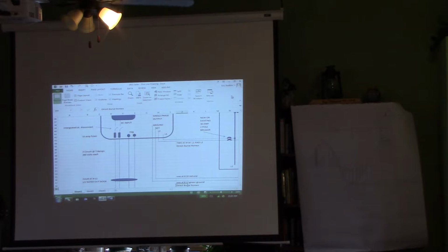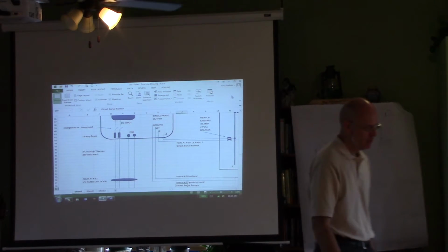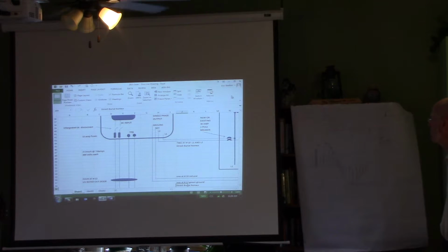Okay. And in June, the sun is way high. So each month, the angle that it comes up and sweeps over this latitude, about 42 and a half degrees latitude, is different. And then these vertical lines mark the hour of the day. And when you look into the plastic, you'll see a tree or a roof of a house. It'll throw a shadow on the plastic, and you can mark the piece of paper down here. And oh, okay, I've got a tree blocking at 7 a.m. in June through March or whatever, and you can mark. So that means that if I put my solar panel here, that particular time period, I'm going to shadow my inverter's power. And I'll pass that around. You get a feel for that. And then next week you'll go outside and work with that, unless Mark wants to, or else Eric wants to do that today.